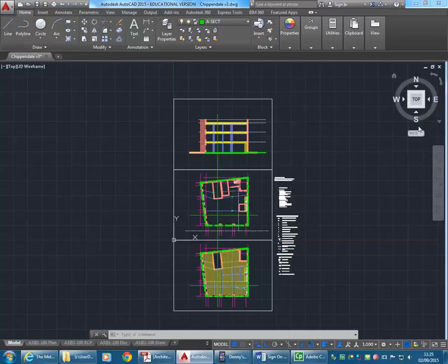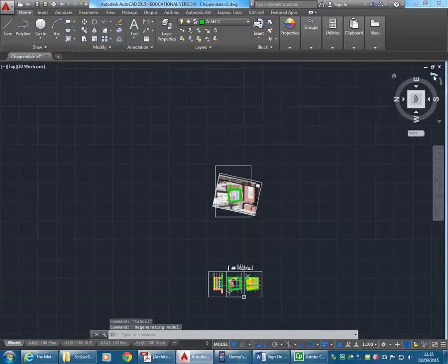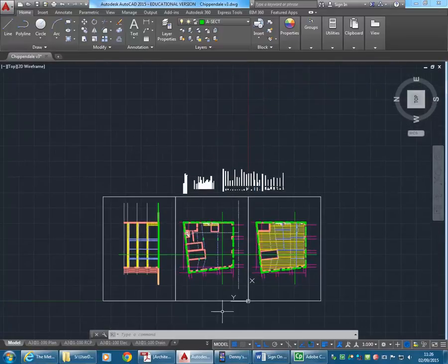So using the view cube here, you will see the arrows won't come up initially, but once you hover near it, you'll see those little curved arrows. And if you click on one of those, it'll rotate in 90-degree increments, which is extremely useful when you're projecting in orthogonal planes, in other words for plans, for sections and elevations.